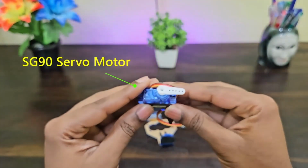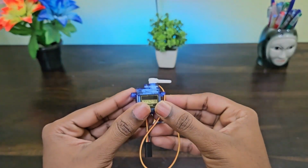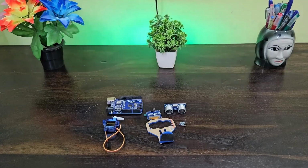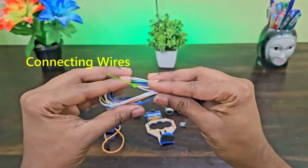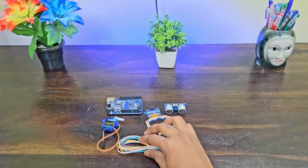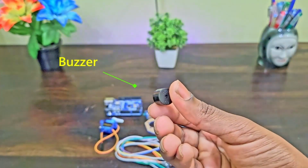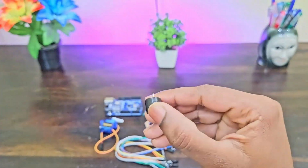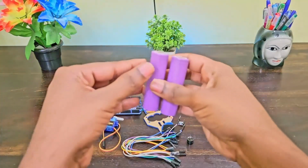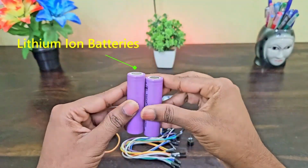A servo motor will control the sweeping motions of the radar, while a buzzer will trigger alerts when obstacles are detected. You need a bunch of jumper wires to connect all the sensors to the Arduino UNO. A buzzer serves as an alert system, producing a sound notification when an obstacle is detected within a certain threshold. We are using two lithium-ion batteries as the power source for our system.